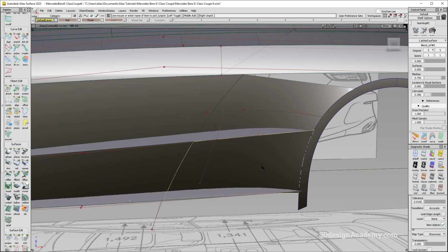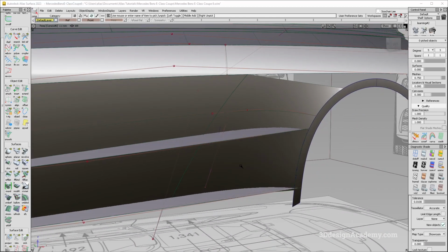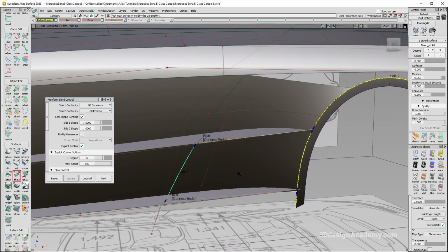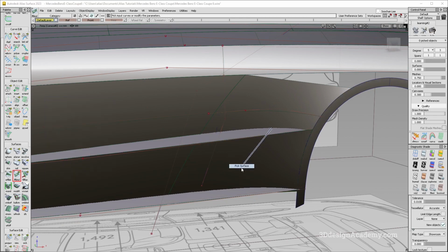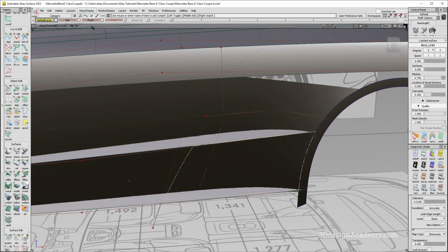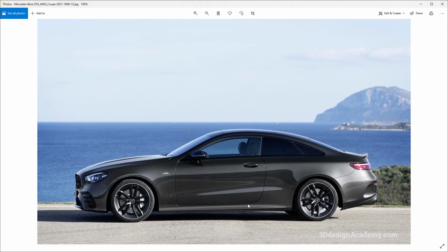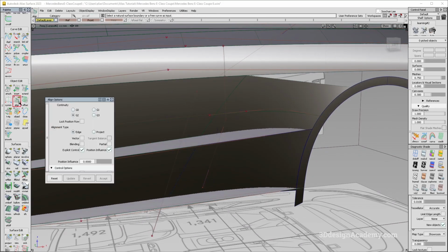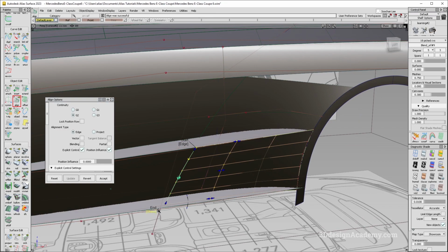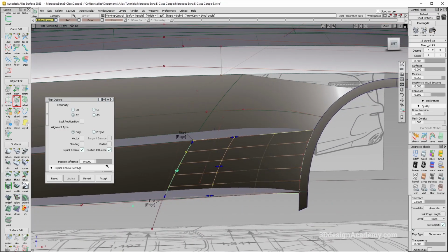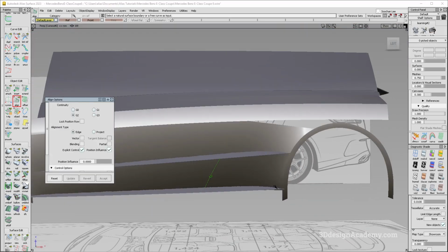So what I mean is you'll see that it starts very gentle and it hooks towards the end. So what I can do is, well, let me just copy and paste it so that I can show you guys what I mean. Right now there's a very gentle slope from here and it suddenly kicks in like that. So I'm going to align this piece over here like this. You don't have to make it edge, but auto scale G2 is on, and I can just push it in a little bit, so that way you'll get a nice